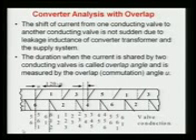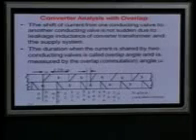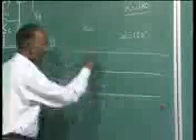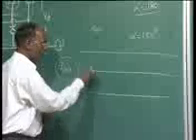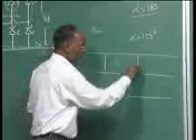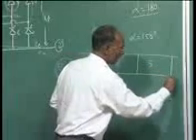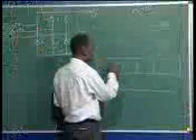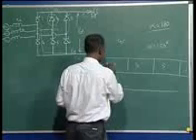To show the commutation here, again this was the case. Now I can say here we have these two lines, upper limb valves and lower limb valves. Here I can say 1, here it was 3, here it was 5, and again 1, and so on. The conduction of each here was 120 degrees.